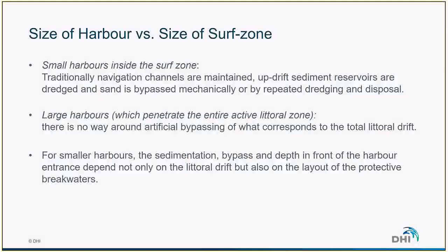So it completely blocks the sediment transport along the coast, and that's where the impact on the neighboring shoreline is the most important, because absolutely no sand from the updrift location is reaching the downdrift area. So that's a big problem.